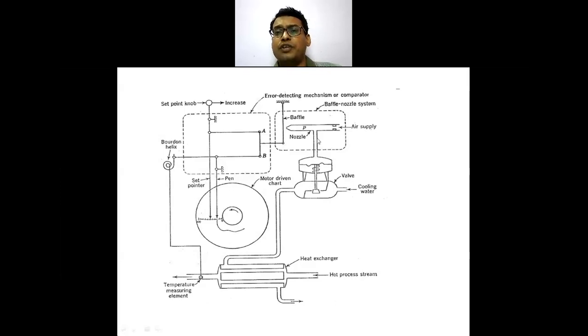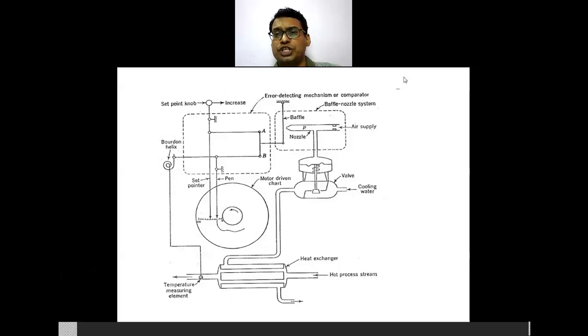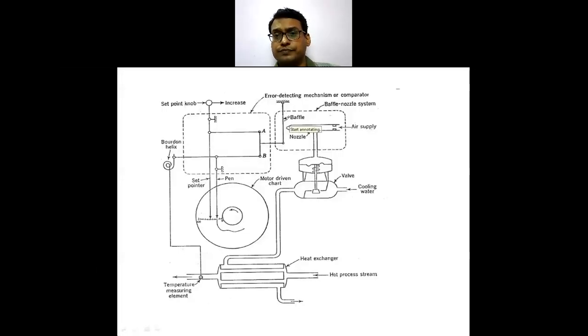Depending on this output position, your baffle is going to change its position towards the nozzle. When the baffle comes towards the nozzle, I am restricting the outlet flow from the nozzle. As a result, a back pressure develops.